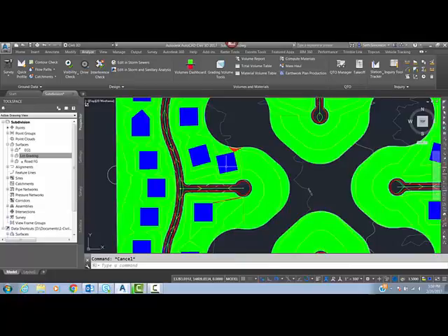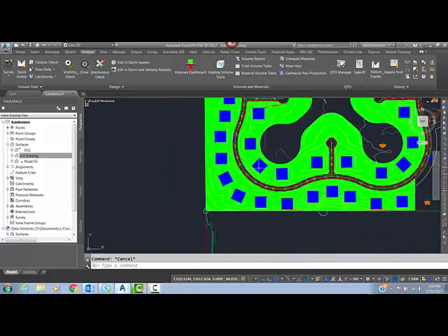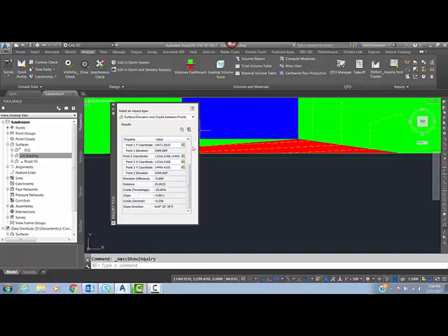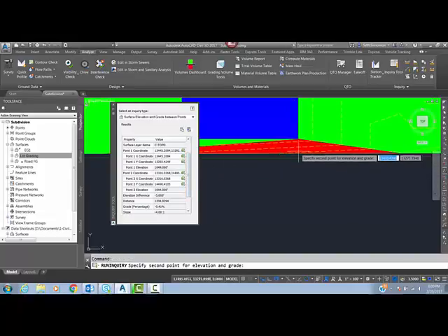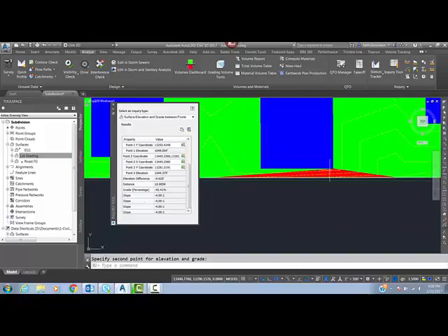Again, when we apply smoothing to it, it probably will go away. And this is just an issue with the contour line stuff, so I'm not worried about that. Okay, the back lot here, let me do another inquiry tool and pick my point 1 coordinate as this point, my point 2 coordinate as, say, this point. Accept that. Okay, so it's 42% right in here, so it's a lot more than what I want, so I would probably have to do some changing in here.